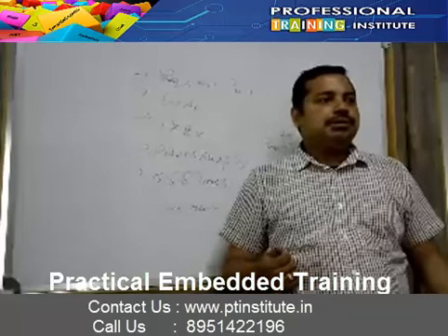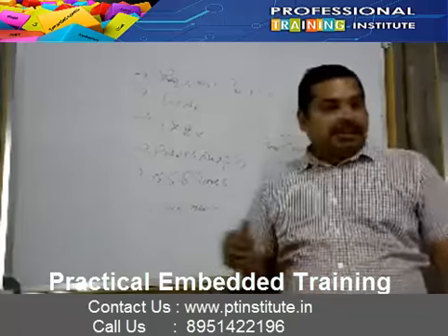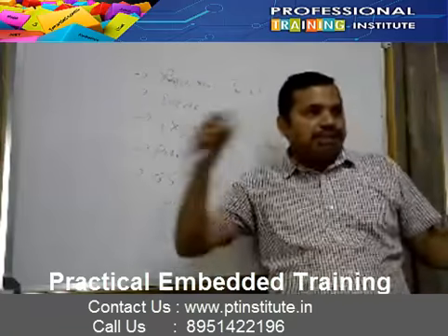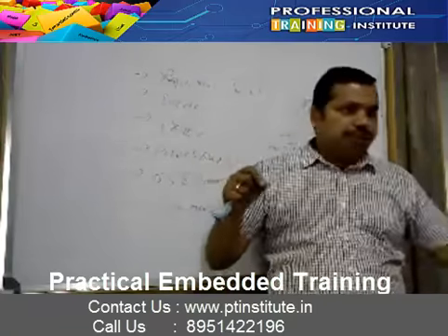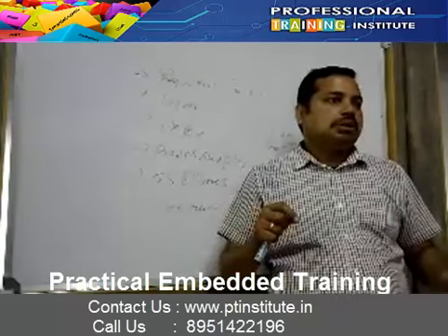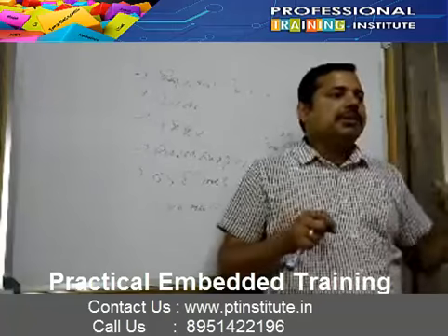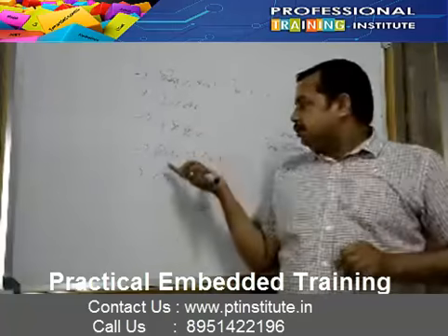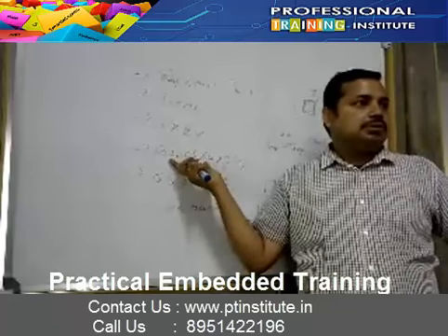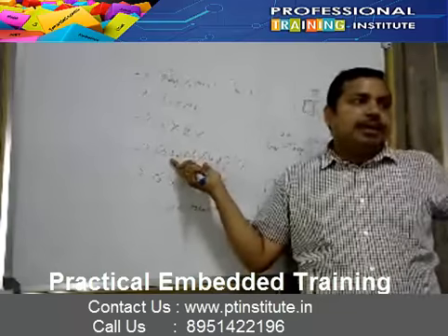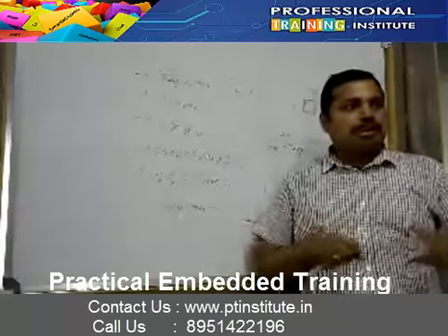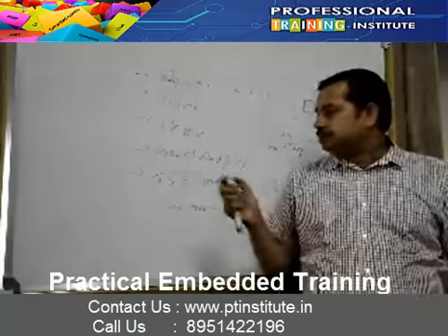Okay, fine. Then about the class, they will tell. Transistor, you check as a switch. You give 5 volt, check whether output 0 is coming or not. You give 0, check whether 5 volt is coming or not. Understand? Whatever we learn, that you have to check. Power supply, you have to make a 5 volt power supply. Every component I will give, you have to just make it. You have to do soldering and the other part.